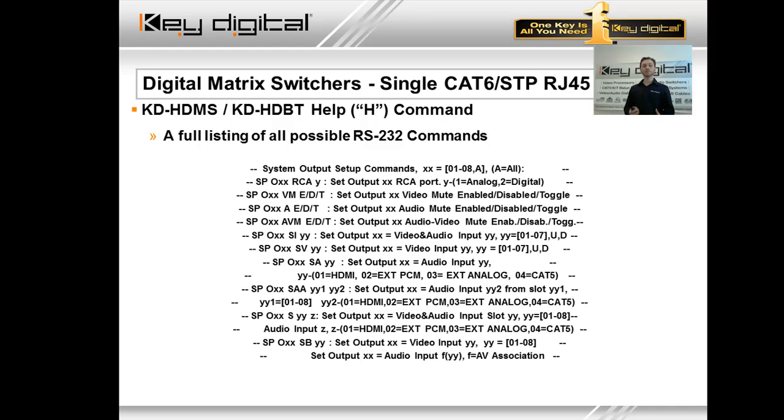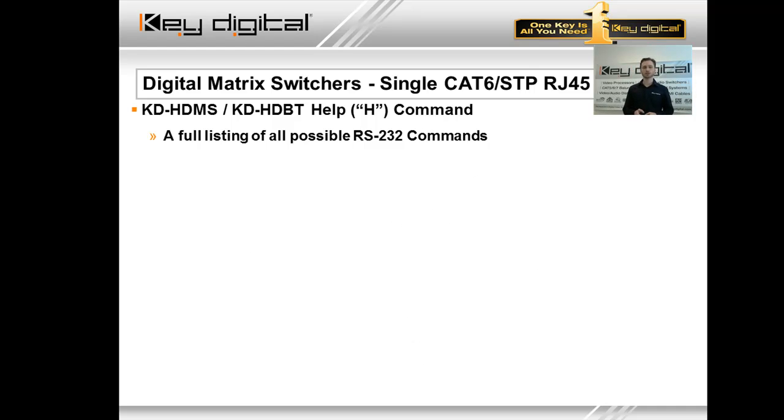So when we think about switching, without spending a whole lot of time talking about it again, you're going to hear us repeat it. Just remember, there's really 3 variables to every switching command with these products. For video, what is the card slot? We've already determined in our initial setup on the input side, when we're doing a video switch, the input slot is already determined. Is it on the HDMI or is it on the Cat5? It's one or the other. Again, we talked about that. But the other 2 remaining variables: the video is just a card slot, audio, card slot, and then the second variable for audio, within that card slot, where are we taking the audio from? So that's why there's 3 variables for every switching command, not just 2.